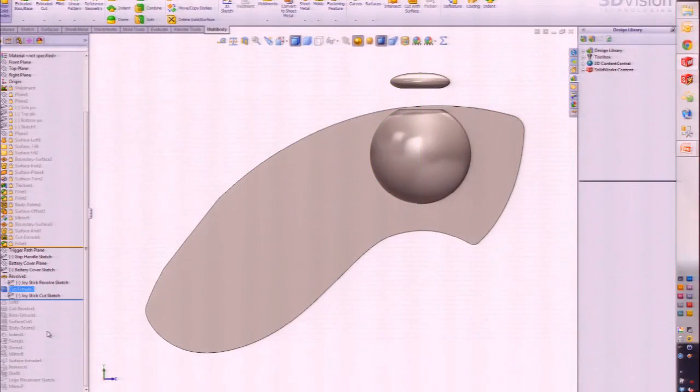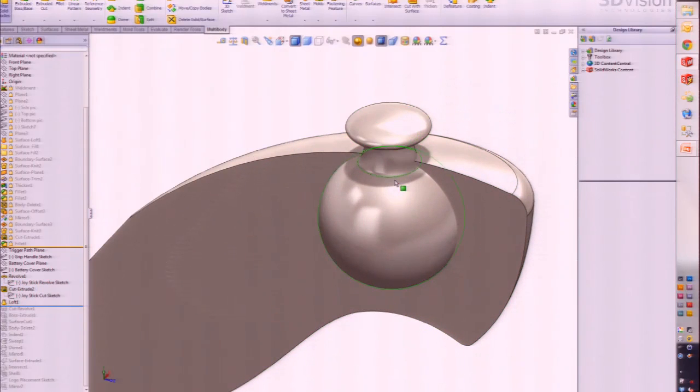All right, so moving on. A really simple feature, the loft command. Some people are intimidated by it, but it's extremely easy if you're modeling between 2 separate faces. You just click on one face, click on the other face, and it's going to create a loft in between those. And you have some blending options for making them tangent to the surrounding faces and whatnot.